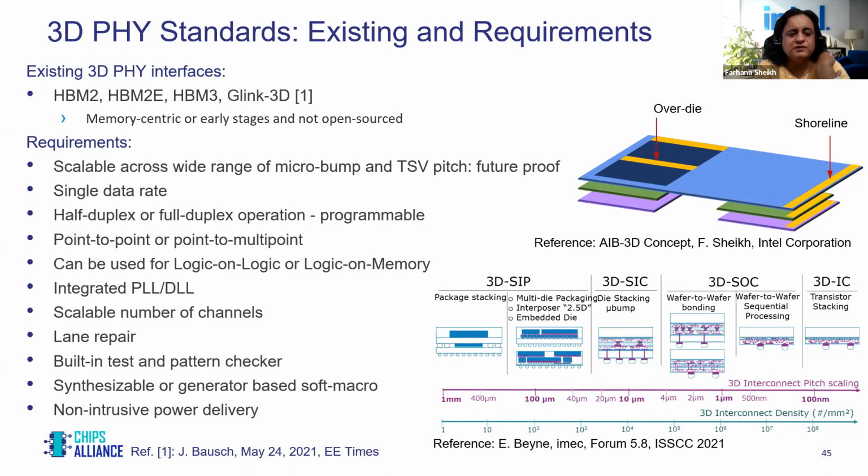Now, for us, what we want to do is we want to be able to support, as you see in the figure to your left on the top, an overdie type of integration of the PHY standard, and also on the shoreline like we're used to with our 2.5D standards. And we want this to be scalable across a wide range of microbump and TSV pitch, and this is just for future-proofing the standard.